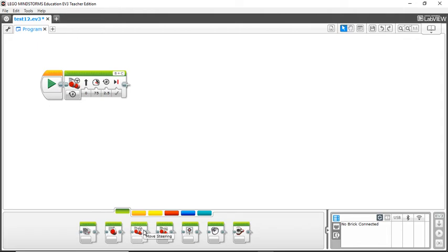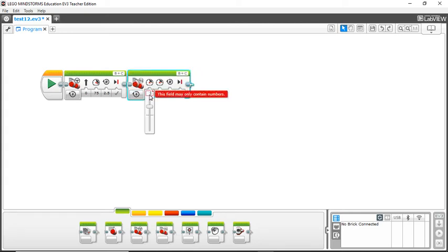We said we want to turn a little bit, so depending on what kind of turn you want, let's just say we want a 0 turn, so let's put this in here, just say negative 5% power, 5% power, because with a 0 turn, you don't want to turn really fast, otherwise you'll get inconsistency. This is pretty fast already, your turn. So let's just turn 0.2 rotations.